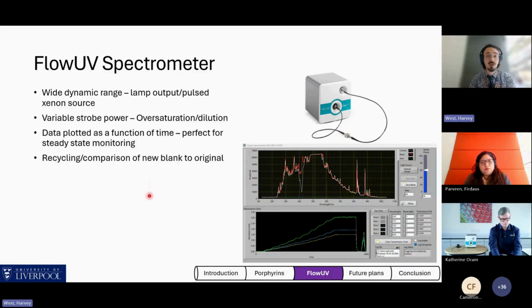current time. We're also able, through the use of switching valves, to purge our flow cell and pump our blank solution through, comparing our current blank measurement to our recorded blank measurement shown in red, allowing us throughout the day, and this is particularly helpful for long experimental runs, to assess if there has been any deviation, because sources heat up, as do detectors, but also an awful lot of ambient conditions in your workspace can change throughout the day as well. Temperature, pressure, transient light, for example.